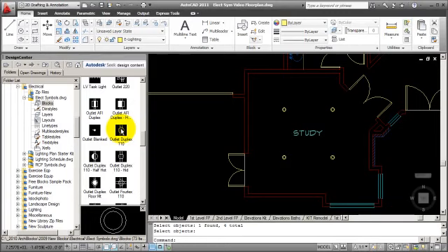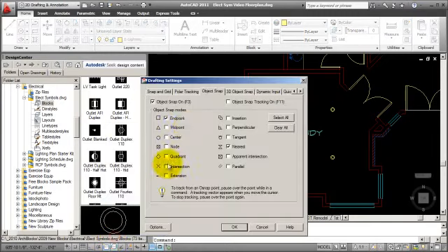And for my first position, I'm just going to drag and drop it over to this wall because it does need to be rotated. But one thing I want you to know is that with this particular task, placing outlets and switches, I go to the running OSNAP, and I go to Settings, and I check off Endpoint, and I leave Nearest as the only running OSNAP on.